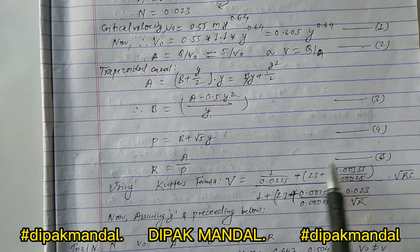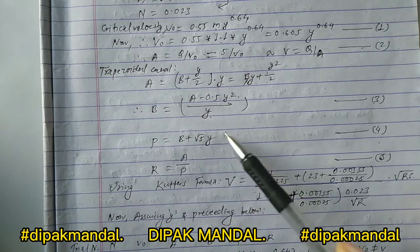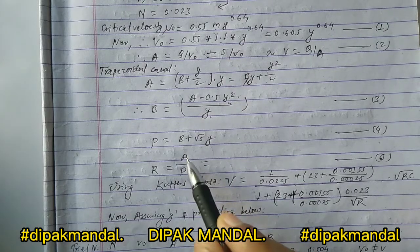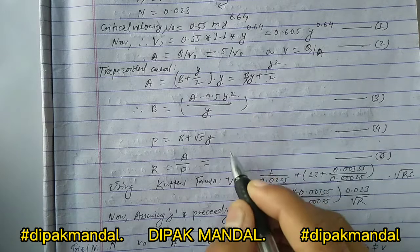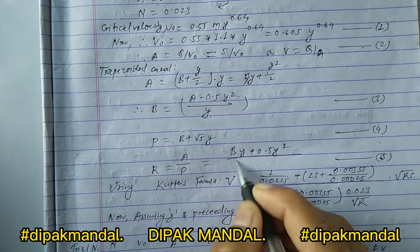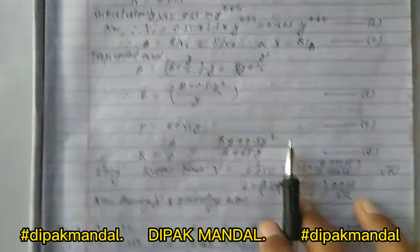Now that the area and perimeter are known, we calculate the value of R, where R equals A by P. You can write this equation as (by plus 0.5 y square) by the perimeter (b plus root 5 y). Let's assume this is equation number 5.